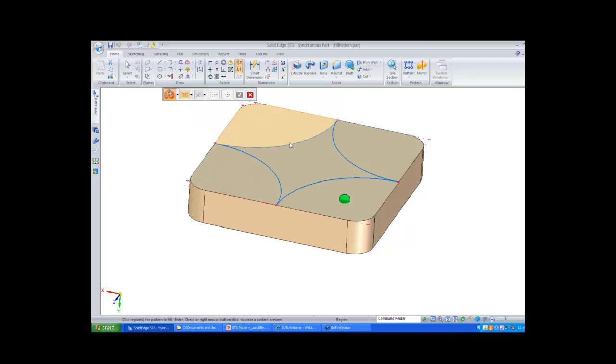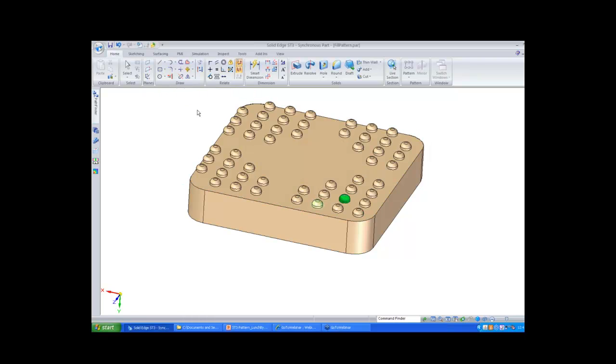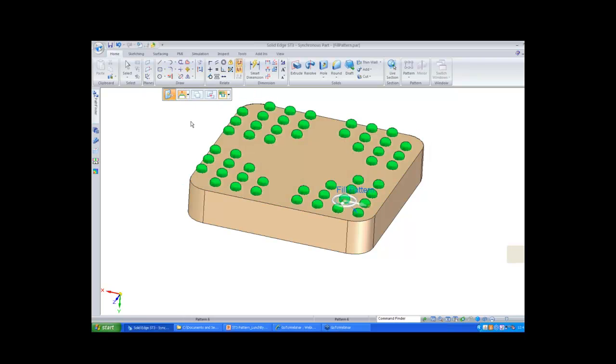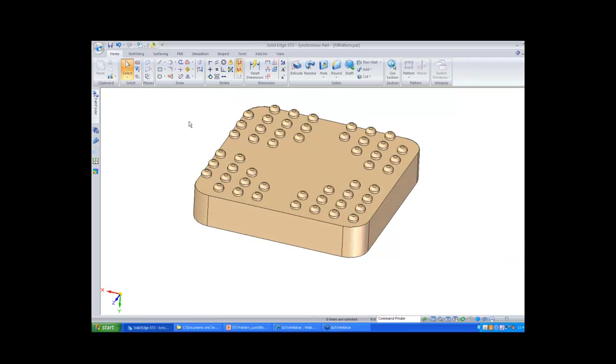So as you hover your cursor on different regions, you'll see these regions highlight. So whatever region I want this instance on, I can just highlight the region, and it gives me options to enter values. So this will be my distance between instances. So I can enter 20, and can generate these patterns. So this was a fill option with rectangular.